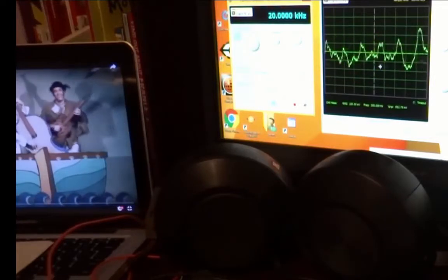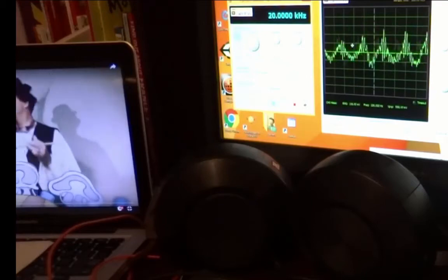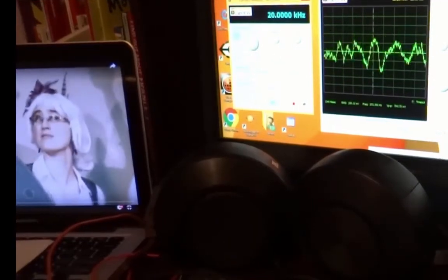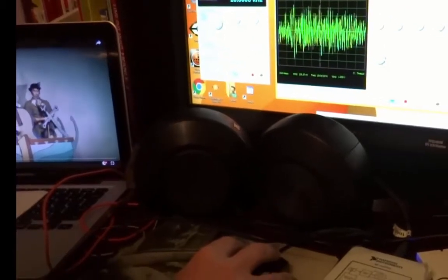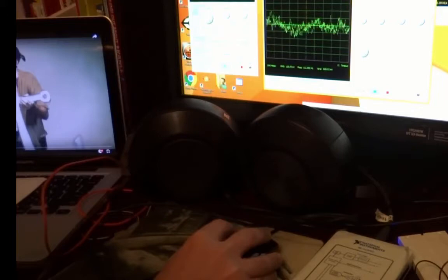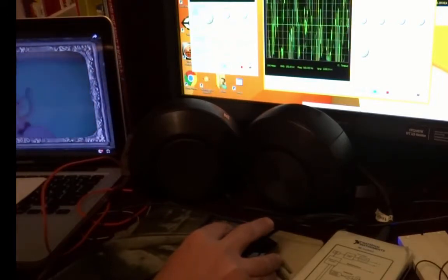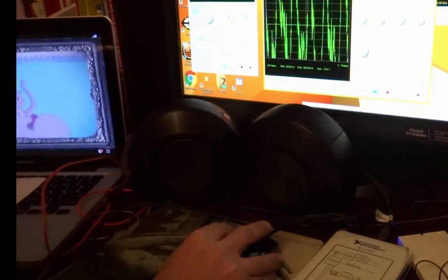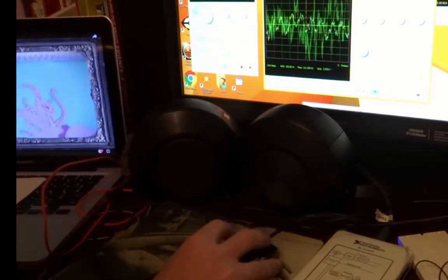Over here on the right, you can also see the music that you're listening to on the oscilloscope. So this is a time domain representation of the signal. I can change the volts per division or the time division to zoom in on the details. I can also change the scale per volt so that it is not too high in one direction or too low in the other, and take a look at it.